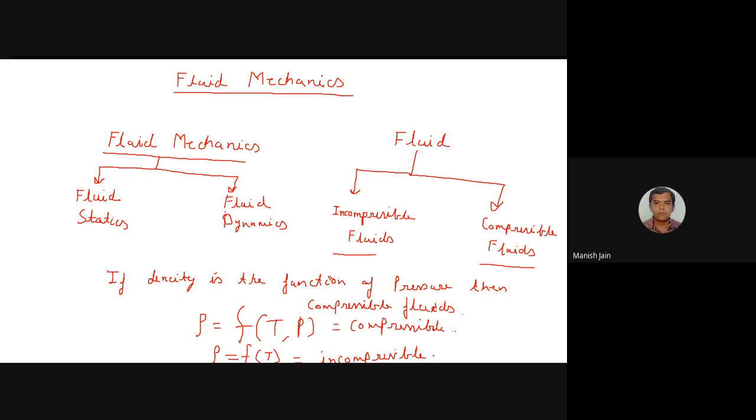So for ideal gases, you can use the ideal gas law. For real systems, you have to take the compressibility factor Z, which you have studied in thermodynamics. When you design a pump for a gas, or when you design a pipeline for a gas, you have to select which type of fluid will flow in that pipeline. Based on that only you can design, because it will depend upon the correlation between density and pressure also.